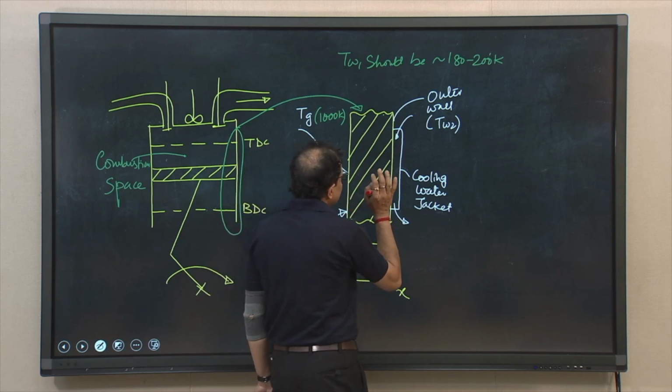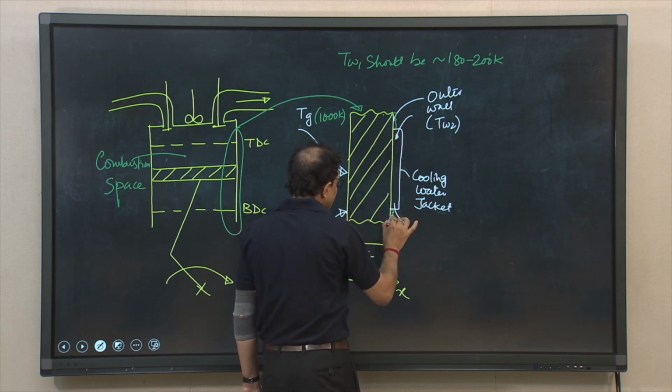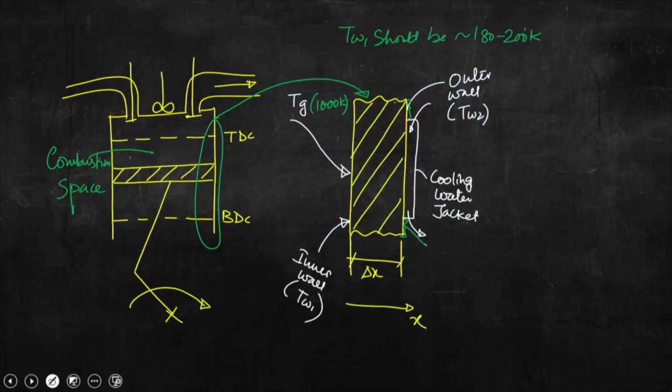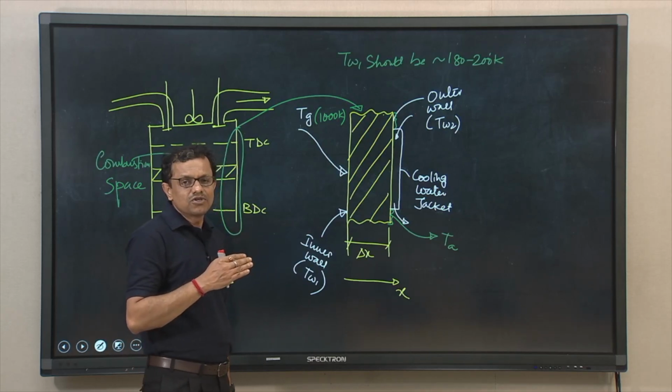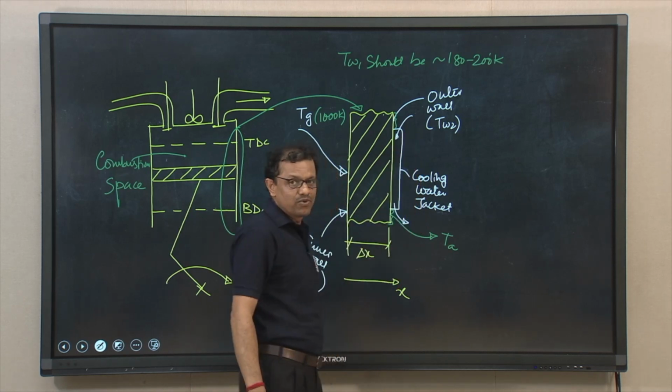And then finally, you can see that these two parts are not in contact with the coolant, so from these two surfaces again heat transfer will be there to the ambient, right. From the outer wall portion which is in contact with the coolant, again some convective transport of heat will be there, and that will be solely dictated by the flow of coolant.